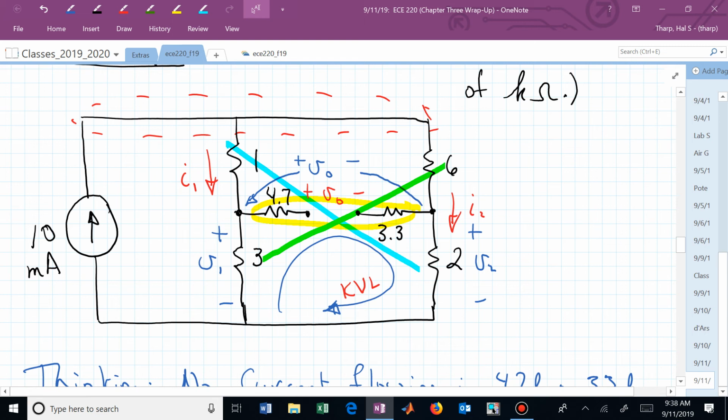You could adjust any of these until you did have that paired product equaling 0. In a Wheatstone bridge, you might put in an unknown, and you're adjusting R3 to get 0 current through that bridge. And then you know how to find R4. It's just the product and division of R1, R2, and R3 from that equality. Question?